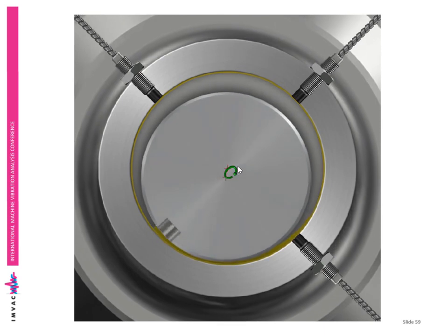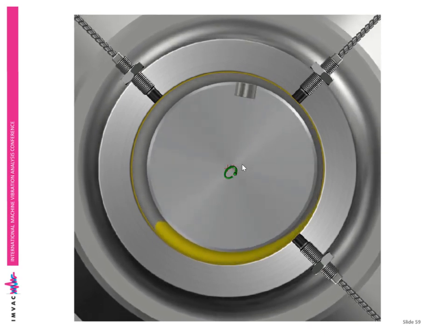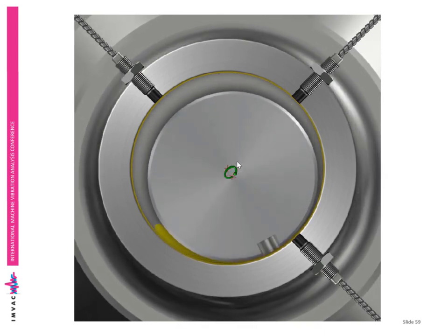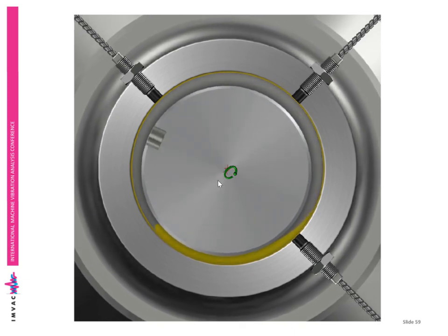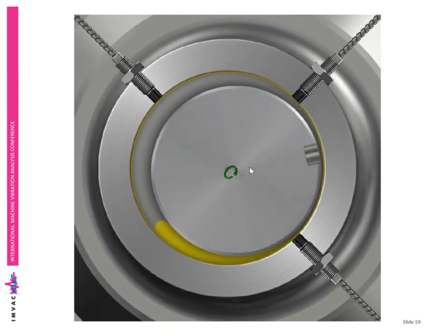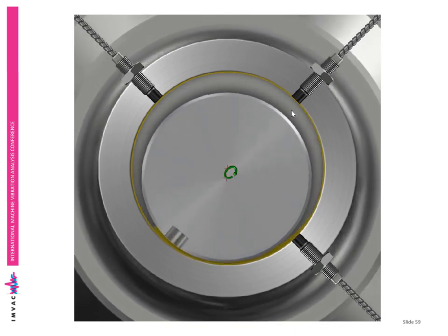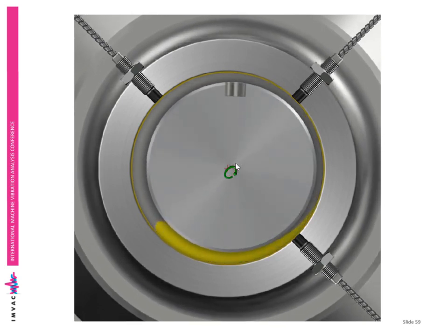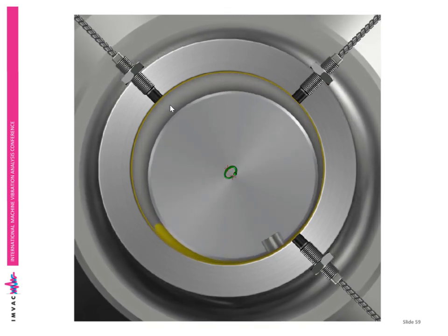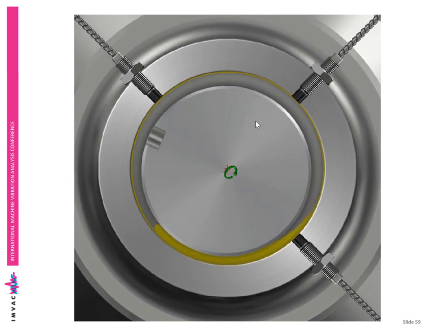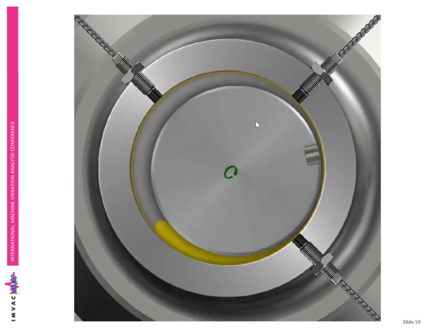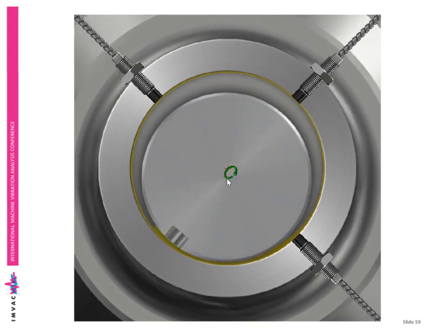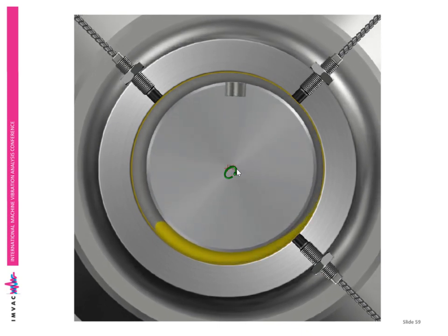So in this case, I'm showing a little orbit here. I'll explain that in just a moment. But it is moving in this circular, actually elliptical motion, and these two probes can tell us that because they're constantly measuring how that distance is changing. It's kind of like triangulation. In essence, it's telling us how the center of the shaft is moving.